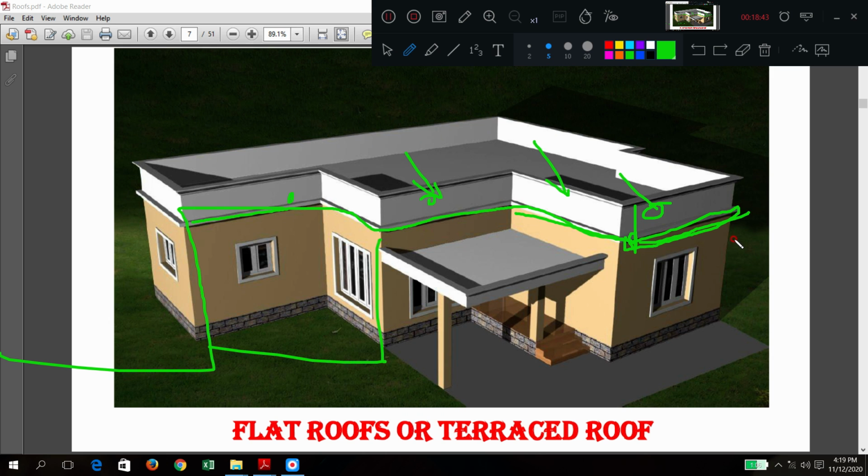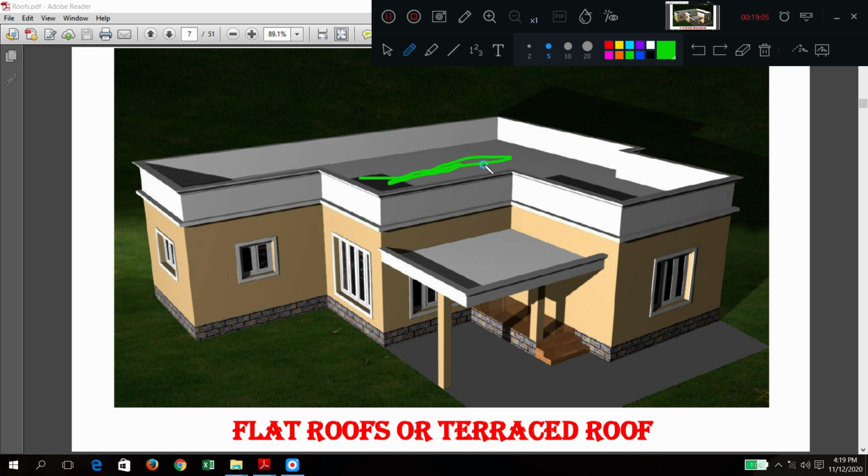Another very important thing is waterproofing. We should waterproof. Otherwise, the pipes may get blocked, so water will not be disposed of, and over time the water will start forming a pond-like structure. To avoid that, you should also have a waterproofing membrane. How can we do it? Proper finishing, a very smooth finish so that water will not penetrate. Sometimes you can go for flooring tiles also. Bituminous products can also be applied.